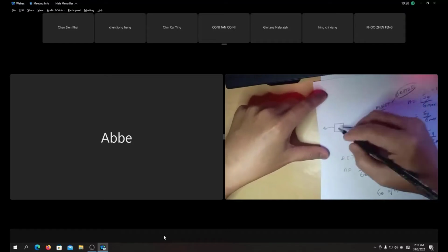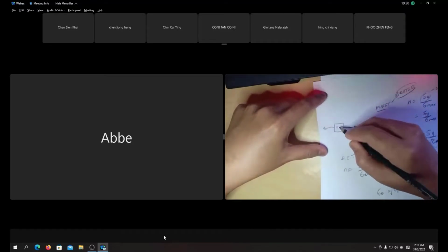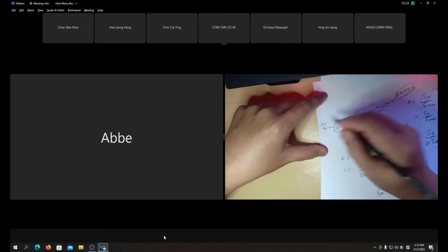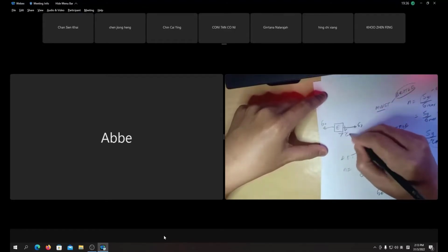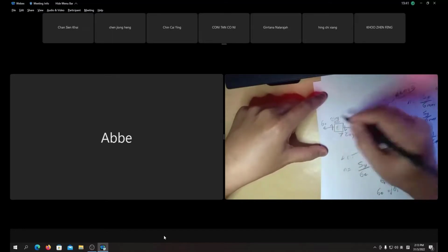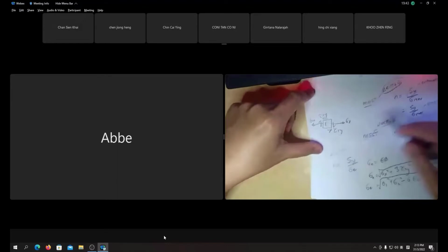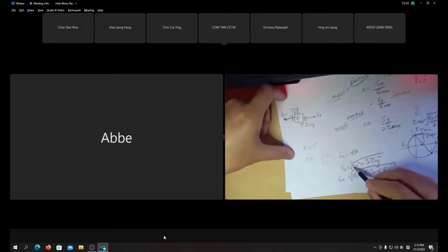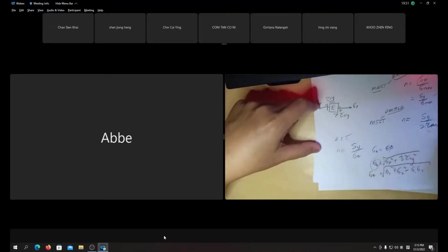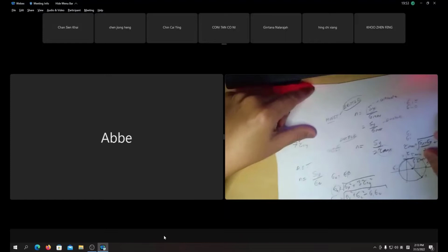In your element analysis, sometimes for a shaft or any case, you only have sigma x and tau xy. I already mentioned this to the class. So you don't have to calculate sigma 1, you just use this first equation, sigma x squared plus the other terms, and you get the equivalent stress. Then your safety factor is Sy over that stress.